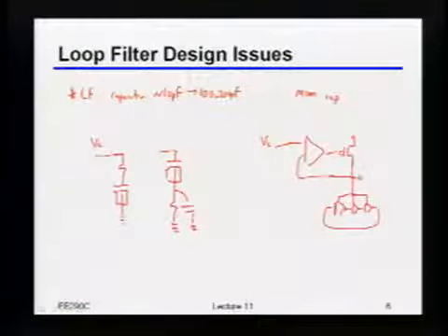So if I've got a bottom plate cap down there that's in parallel with the resistance, remember the resistance was there in the first place because I needed a zero. So if I now have an extra pole there, I could basically completely screw up my stability. Okay? So indeed, you typically will end up building it so that it looks like this. At least if you have an NMOS, in fact even usually with a PMOS with caps, you'll usually build it like this.